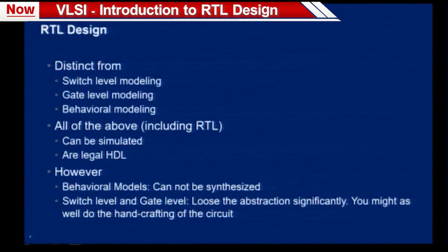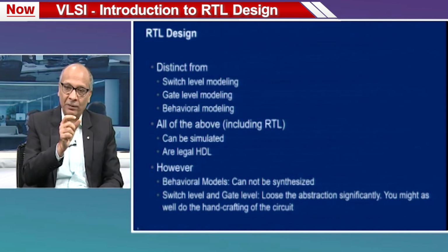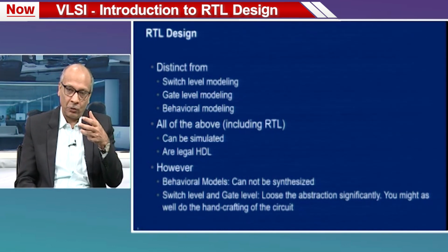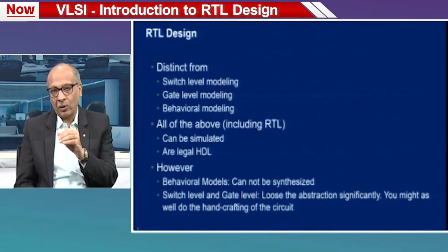So, let us now come to the basic logic design. In today's technology, most of the basic logic design is done in RTL design. Okay. RTL stands for register transfer level. Now, RTL design is distinct from switch level modeling or gate level modeling or behavioral modeling. Switch is often used in semiconductor circuits to mean transistors. So, switch level modeling means you can specify something in terms of transistors. When you talk about an inverter, you could write a PMOS and an NMOS and connect them together, and that becomes an inverter. So, that is the switch level modeling.